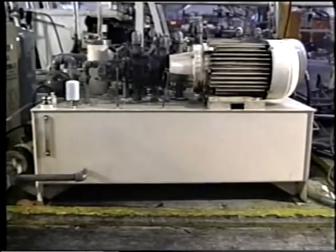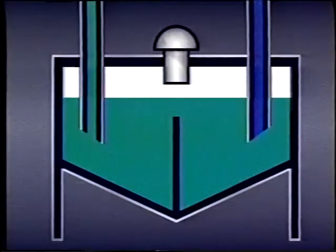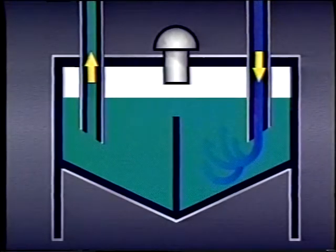Basically, all reservoirs work the same way. Fluid enters the reservoir through return lines that extend below the surface of the fluid. This prevents splashing, which would add air bubbles to the system and could cause pseudo-cavitation. All return lines come in on one side of a reservoir baffle plate that prevents the fluid from being immediately drawn back into the pump. Instead, the returning fluid mixes with the other fluid in the tank.